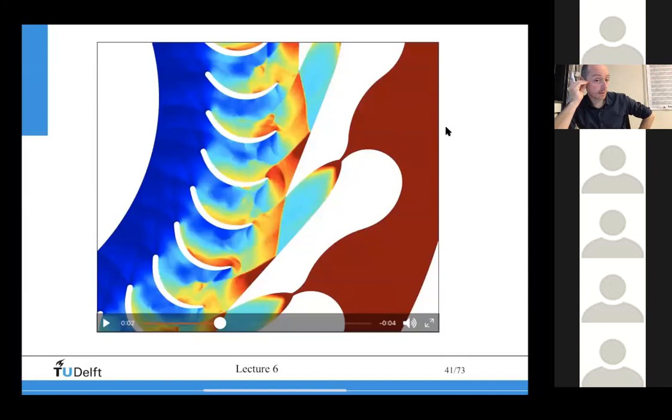You get the heat in this Rankine cycle from the waste heat of a gas turbine or diesel engine or anything else, and then you expand that vapor inside this turbine. Because of the relatively low temperatures and small powers, instead of having several turbine stages with a different fluid, like toluene in this case, you can have in one turbine stage pressure ratios of approximately 100, right?